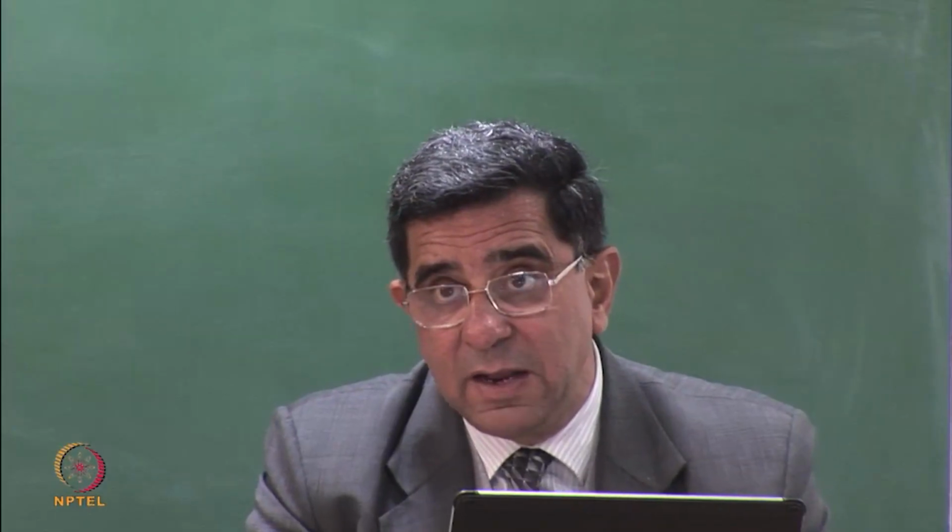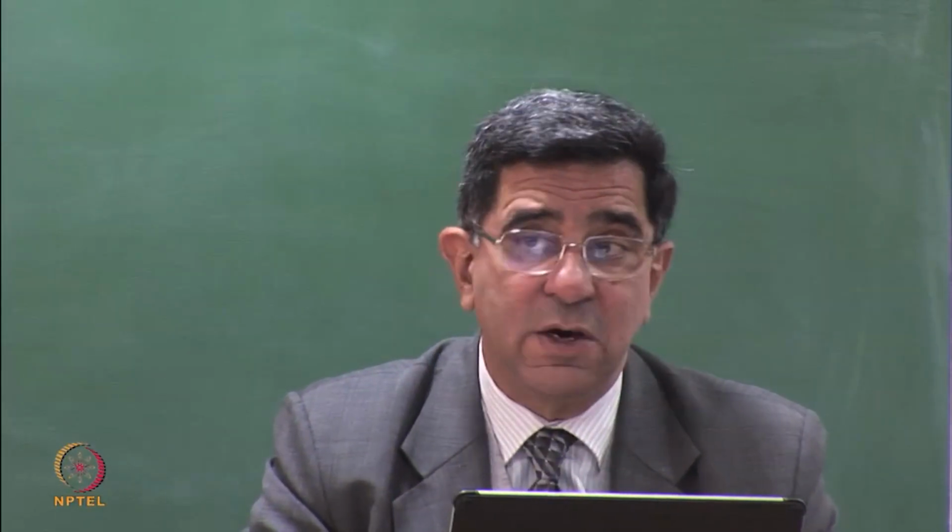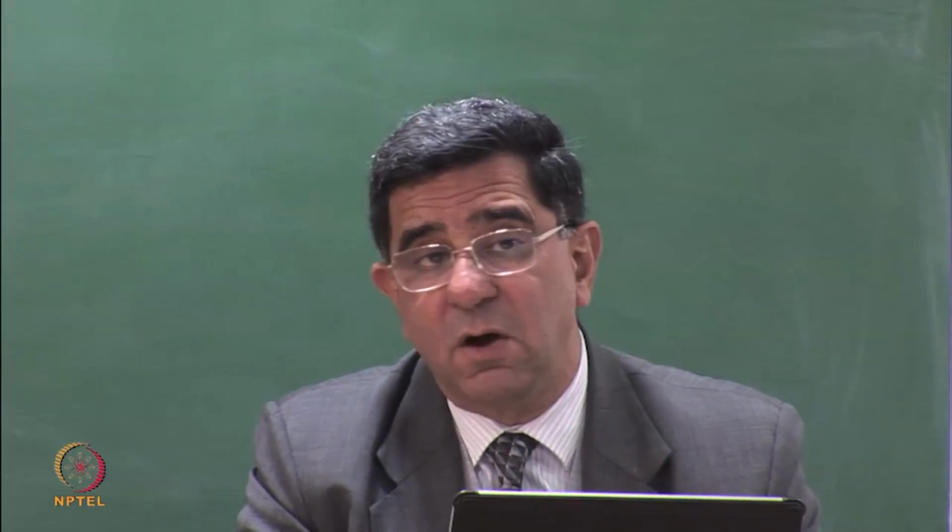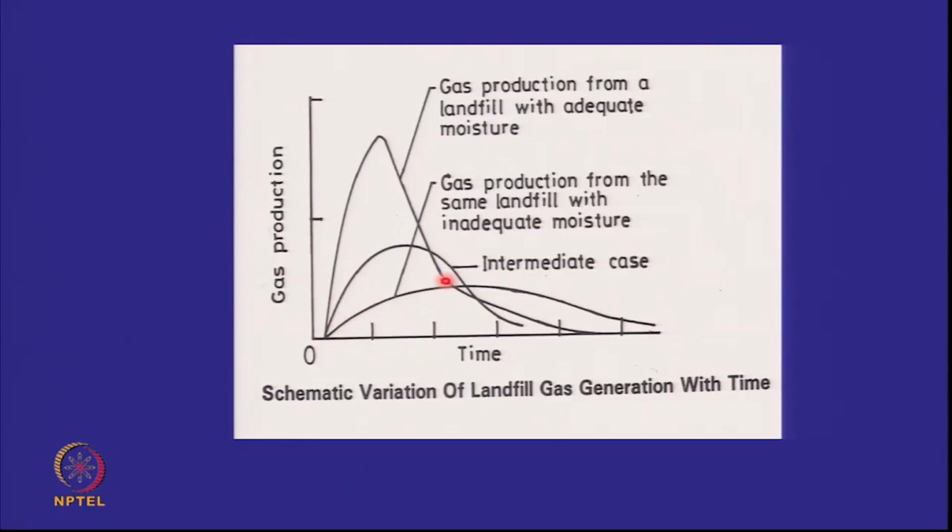However, when we do daily cover and we make a dry tomb landfill, no moisture is available. So the process of degradation slows down. And therefore, this graph shows that the peak is no longer there. It's a much lower production rate, but it lasts for a longer time. In a sense, all biodegradable material has to biodegrade. So if you look at the area beneath this and the area beneath this, they have to be similar. So a dry tomb landfill, the way we are discussing it, may continue to give you gas for 20 to 25 years. So it may not stabilize that fast.